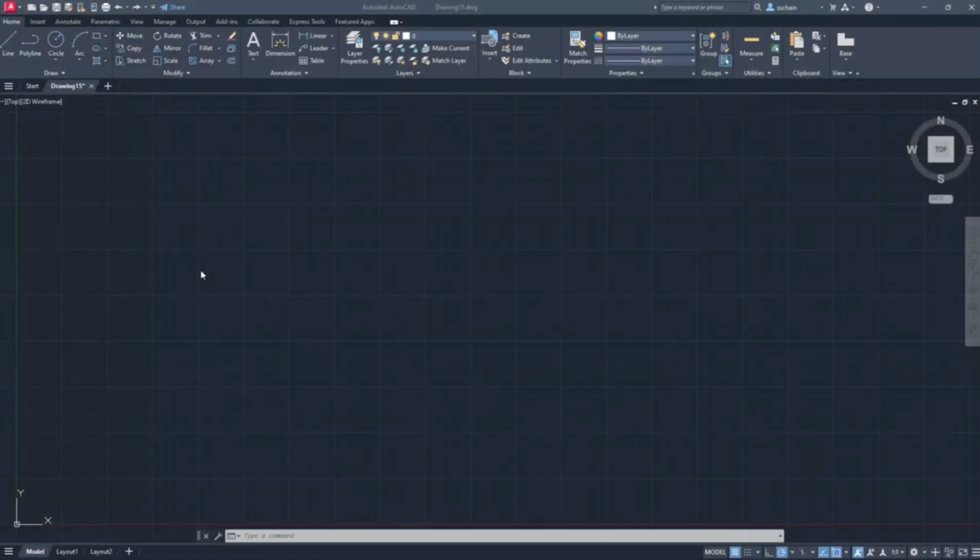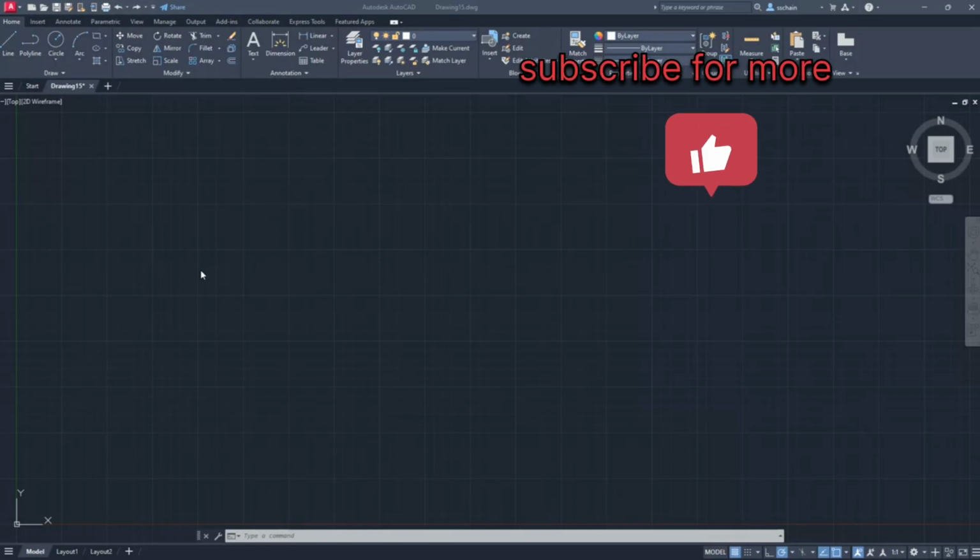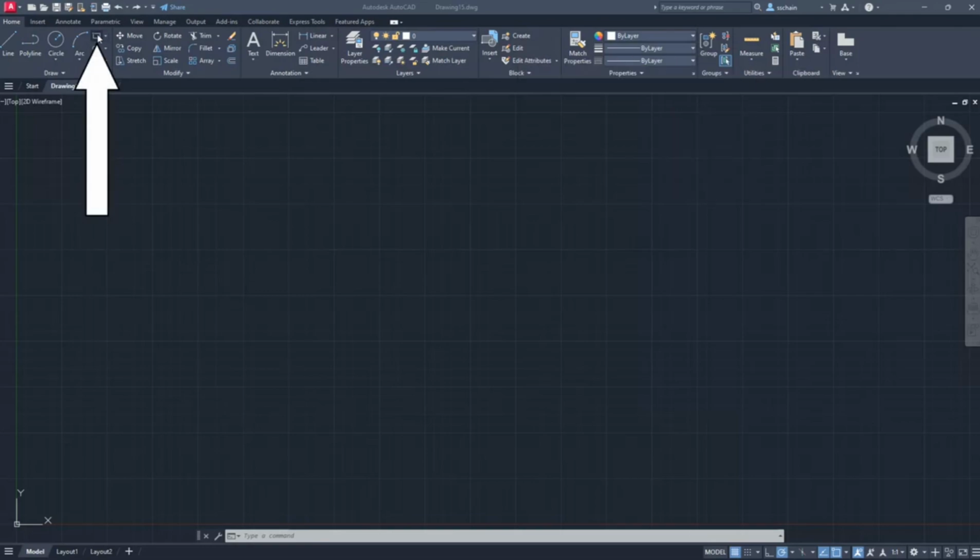In AutoCAD, it is easy to create rectangles. Simply use the rectangle command. This command creates a closed rectangular polyline from specified parameters, such as diagonal corner points, dimensions, area, and type of corners. On the ribbon, Home tab, Draw panel, select Rectangle.